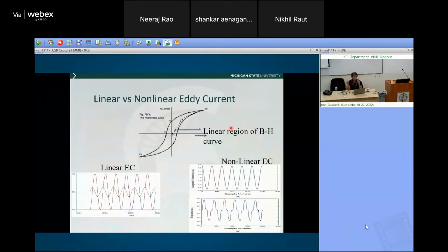See, all those that I talked about so far, we are operating in the linear region. The power is a very low amplitude signal. So we know exactly that for a low amplitude signal, operating in linear excitation mode, the relation between excitation and received signal is the same frequency, except amplitude and phase are different. That's all, like a linear system. Because there is no magnetic material over there, everything is fine.